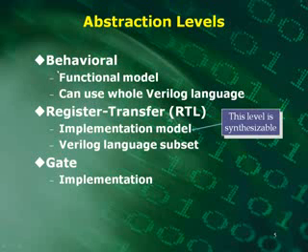You can't synthesize the behavioral level, but it is very useful for simulation purposes, and maybe just to create a functional model to begin with, to test other models with real quick before you actually have the RTL code written. And eventually, after the RTL, you're going to get a gate implementation. It's going to produce real physical gates, ANDs and ORs and flip-flops and latches and all those types of things.